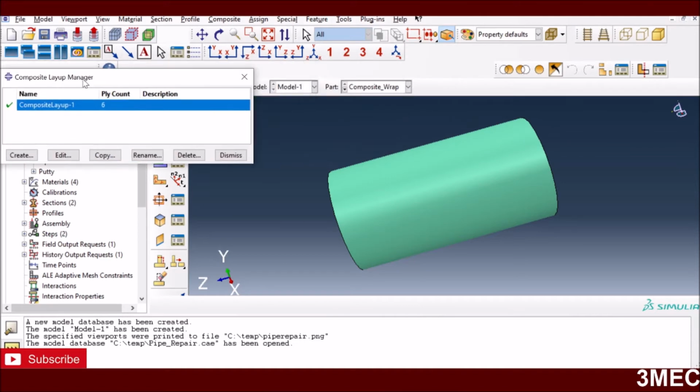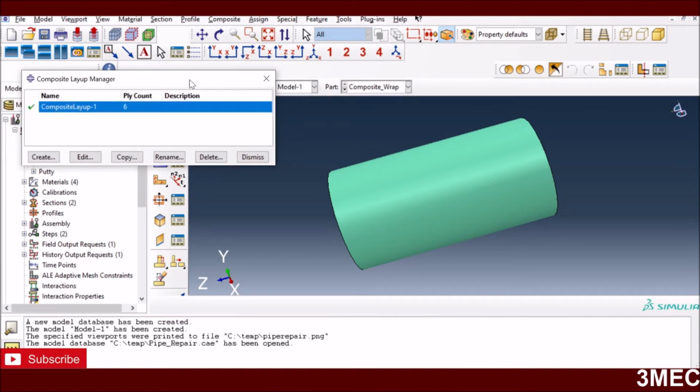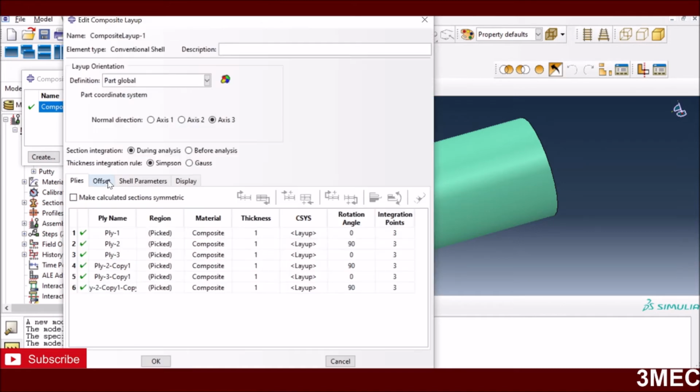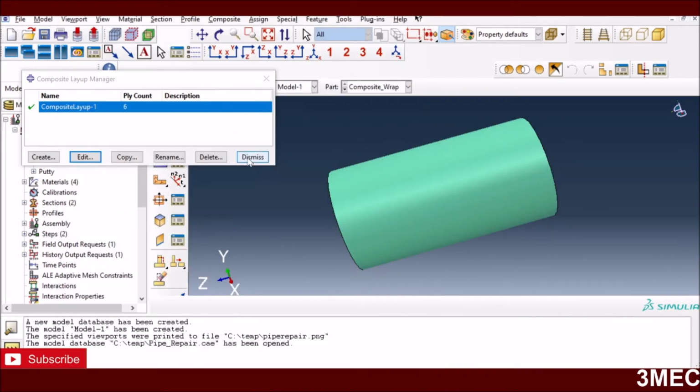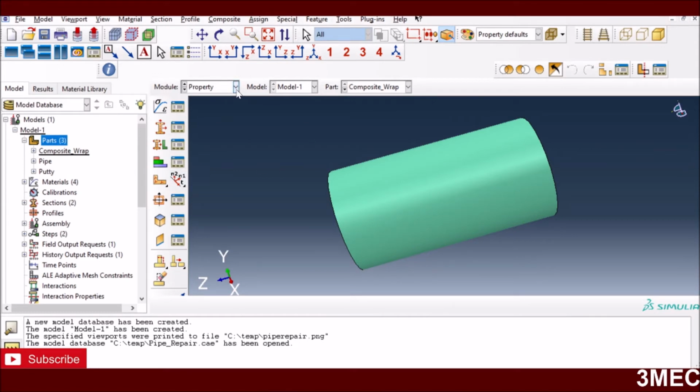As you can see, what they did was they had layers of composite with different fiber orientation, and they had 6 plies in that case after wrapping around the pipe, and I have defined those 6 plies here. So I have 6 different orientations: 0, 90, 0, 90, 0, 90, and I'm using the composite properties which I just showed you before. So this is how I have defined it with the orientation, as I told you before. So this is how I have associated all the properties.